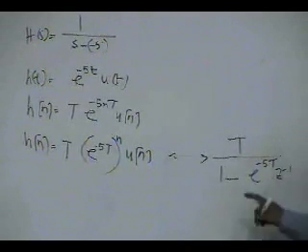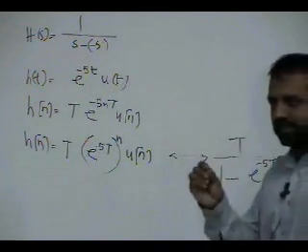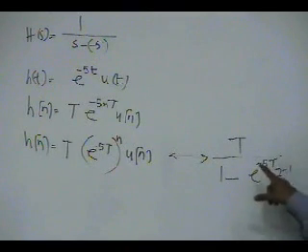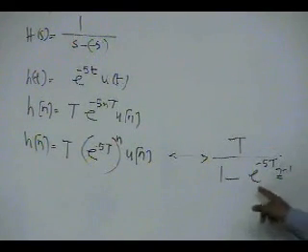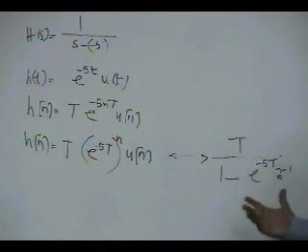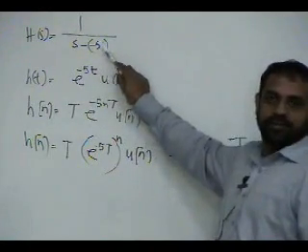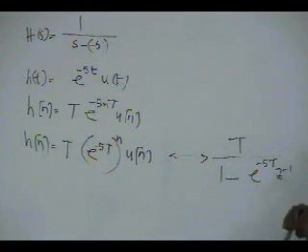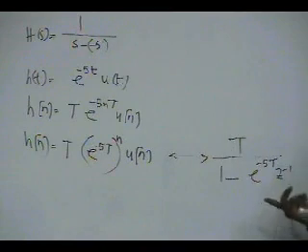This negative value means the exponential is always less than 1. What does it mean then? That this is always less than 1. So what is this in the z domain? It is a pole which is always inside the unit circle, if the exponent is negative. So the relationship is simple: a pole in the S domain will be an exponential of that pole in the Z domain. That is the relationship.